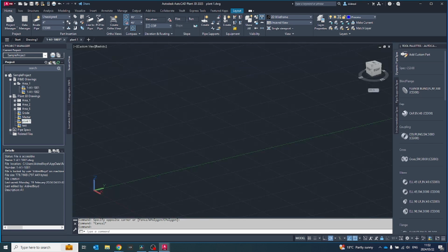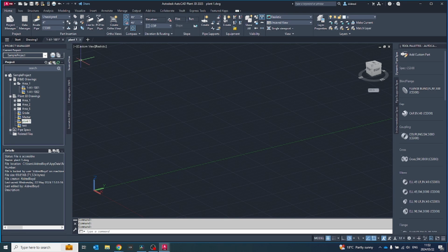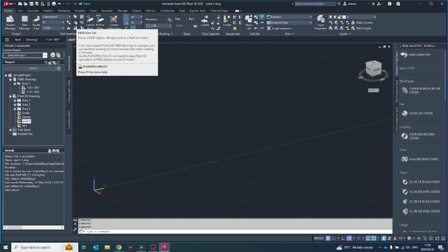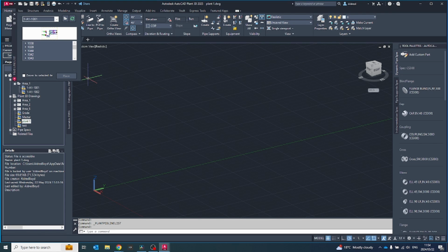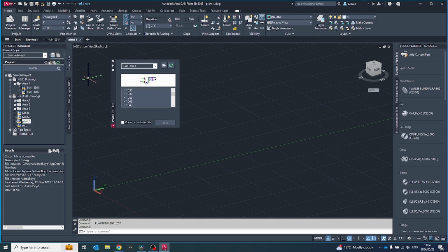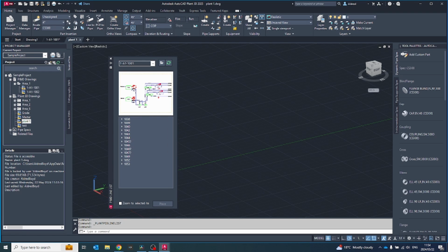Going back to my Plant 1, yes, I could start routing the pipe and then tag it the same as I would inside my P&ID, but there's an easy way to do that, so you don't have to retype different information. On your Part Inspection, you've got a command called P&ID Line List. When I select it, it brings up this dialog, this tool palette.